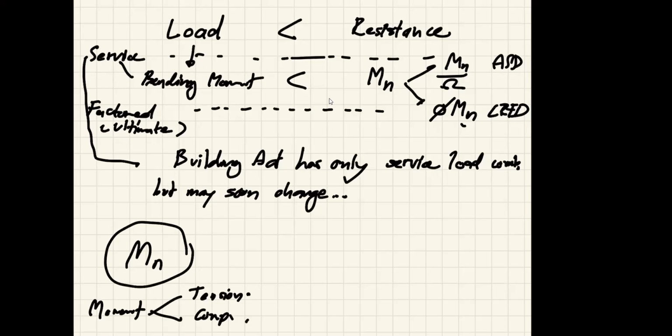You have come this far into the civil design class, so you should know that it's again the compression that is going to cause you problems, because compression will lead to buckling. Because compression exists in your flexural members, buckling will surely occur. But tension will not give you problems, except that your member is going to yield, okay?